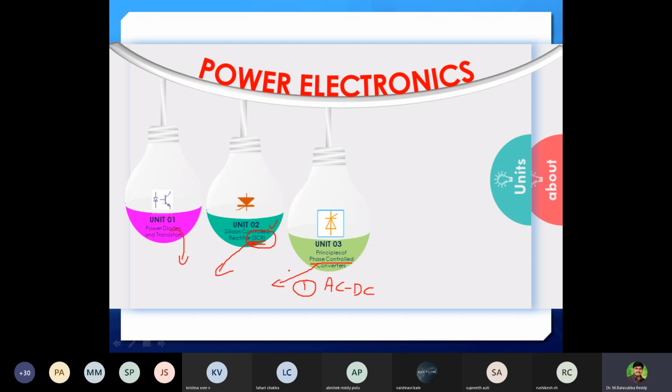From this onwards we mostly use only the thyristor as the device or switch. If I use a diode instead of a thyristor, we call it an uncontrolled rectifier. This we call a phase controlled rectifier, because I use the word control, as the output is going to be variable. Our control is nothing but a variable output, nothing more than that. So a variable DC is obtained.